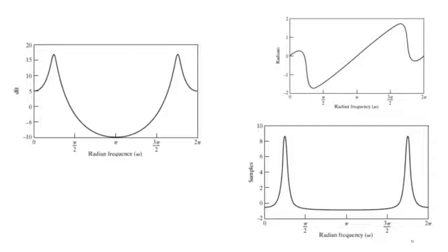If we carefully observe this plot for the frequency response, we find that when the value of omega roughly equals theta, the length of the vector v1 becomes small, because v1 equals e^(j omega) minus r e^(j theta), and changes significantly as omega varies about theta.